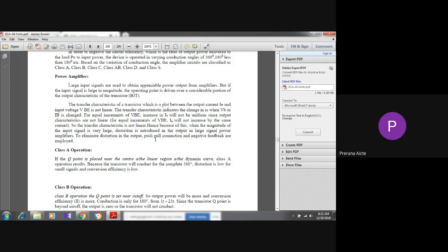You have to make the transistor behave as an amplifier by connecting the circuit in the active region. For the active region, the condition is: input junction is forward biased and output junction is reverse biased. For the saturation region, both junctions must be forward biased, so in that region the transistor acts as a closed, on switch. Similarly, for the cutoff region, both junctions must be reverse biased, so in that region the transistor acts as an open switch.